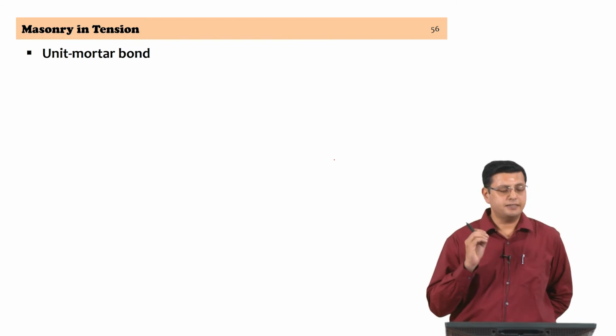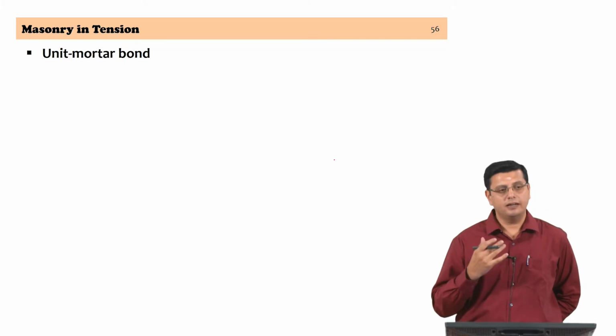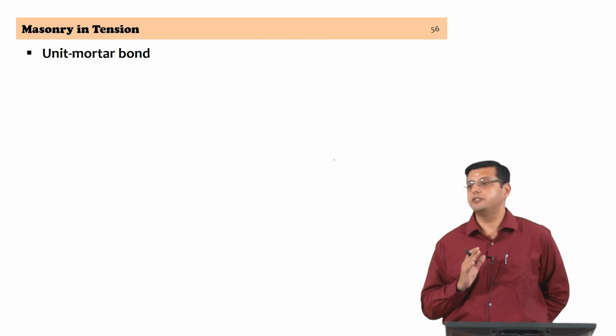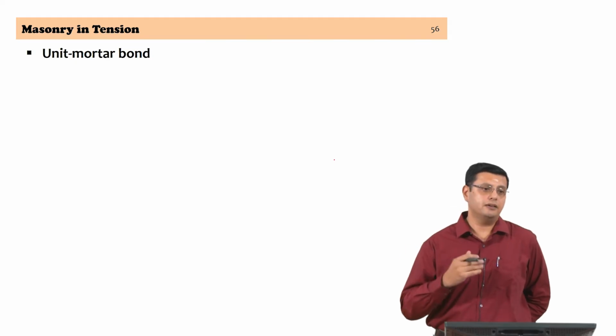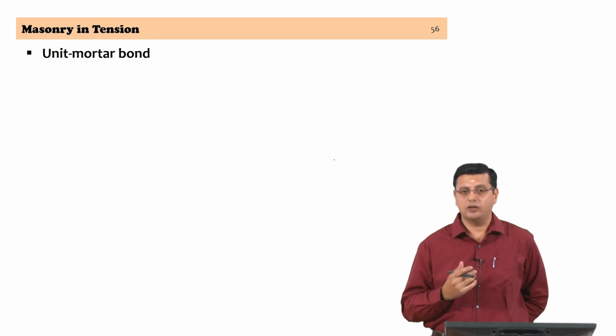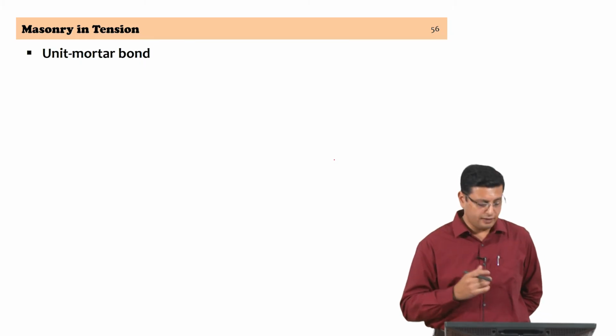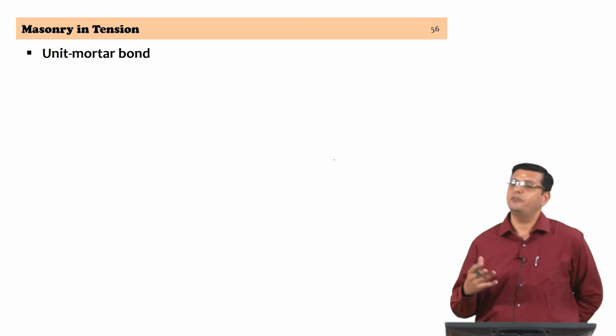The masonry tensile strength is not something that you can depend on, and hence for most practical purposes it is good to assume that you have a zero tension material. So, if there is some tensile strength in the material, that is a cushion that may work in your advantage, though you are being conservative in your calculations. But here what we are really interested in is flexural tension.